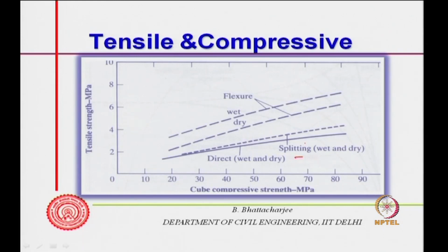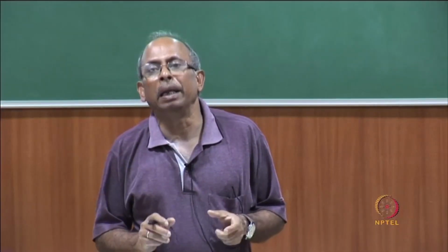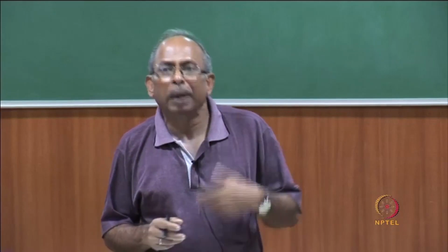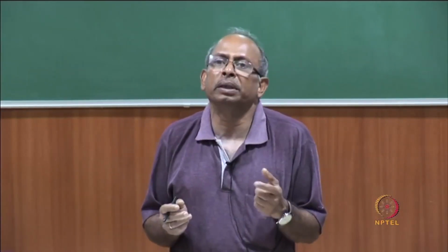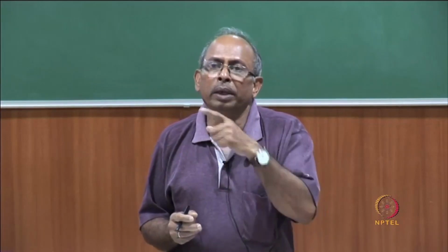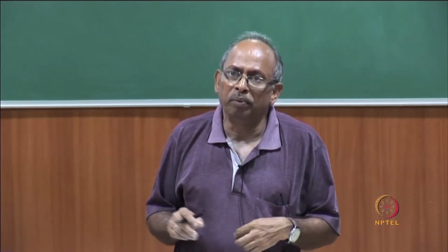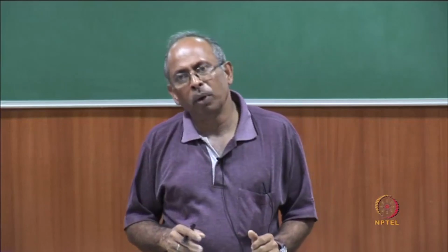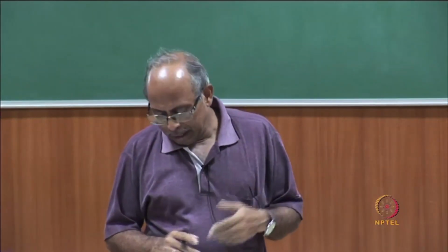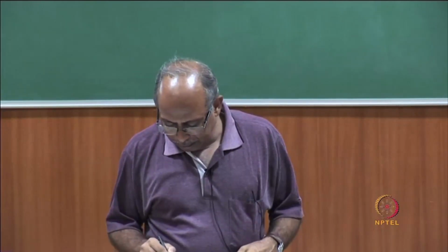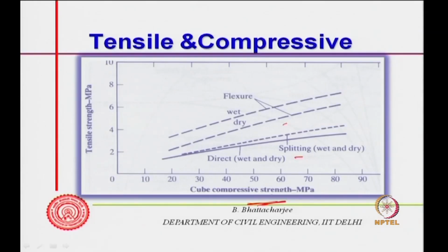And another way is to measure the tensile strength under bending load, because bending induces tension, as we know, in a simply supported system the bottom fiber, with a load at the top, is under tension. So, the concrete we can test in that manner, and that is flexural tensile strength, that is usually higher, and that can be related to compressive strength, in dry and wet condition. We can see that moisture condition also affects the strength, as you have seen.